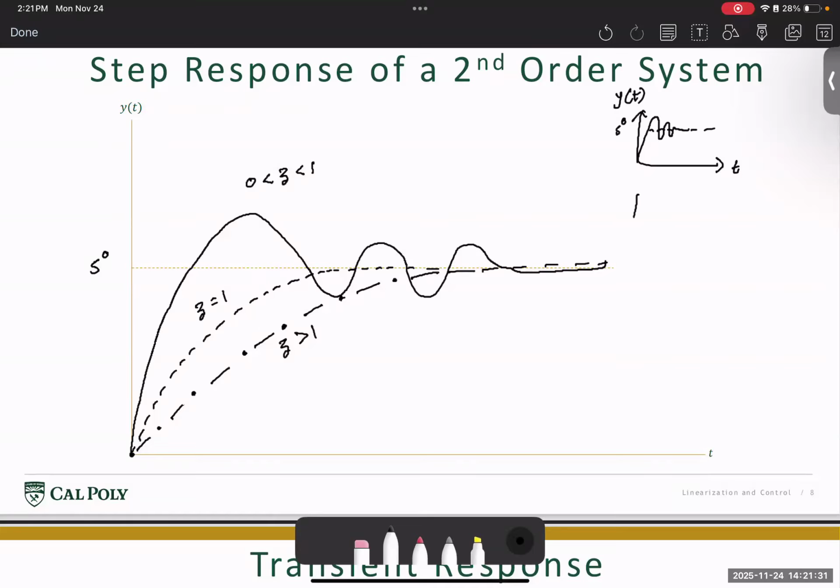But for a typical passenger aircraft, because you look at comfort more than how fast the aircraft actually pitches to 5 degrees, you might be looking at a critically damped or an overdamped system, where you want the pitch of the aircraft to be as smooth as possible before it reaches a desired pitch of say 5 degrees. For a fighter jet, the pilot can be okay to experience a little overshoot and undershoot, where the aircraft goes to somewhere like 5.2 degrees, comes back to 4.9, before it settles to 5 degrees.